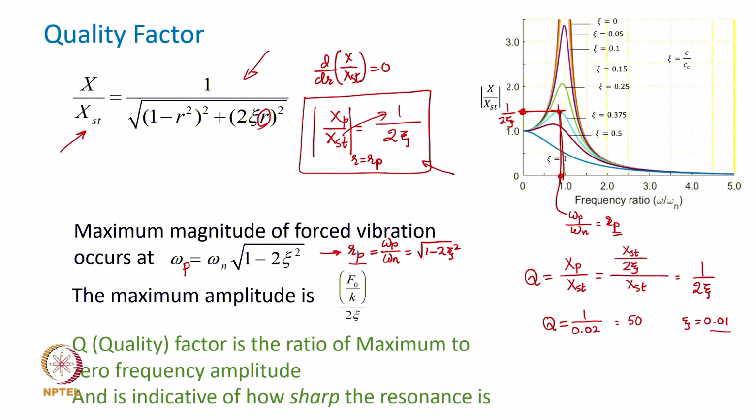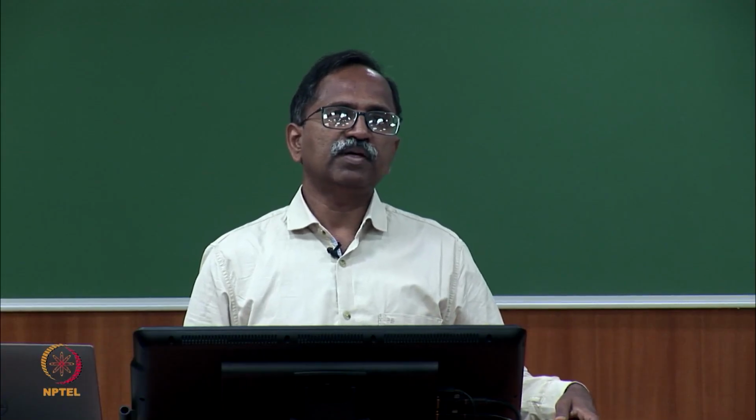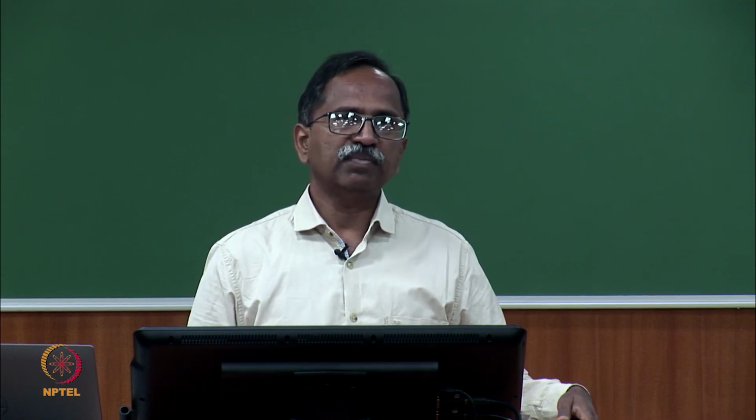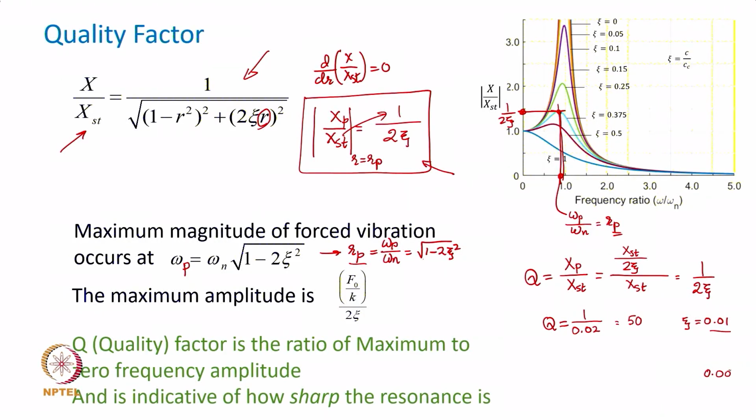You might be aware the equivalent damping ratio, damping factor of structural steel is roughly of the order of 0.0045 whatever, it is in the third decimal place, right. It depends upon the real composition and all, but generally that is the range, it is less than 0.01.